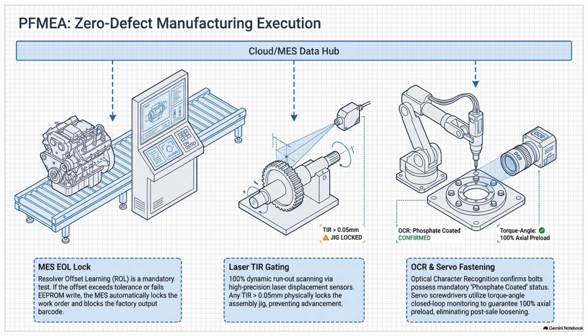The software then instantly mathematically corrects the nonlinear inductance. It counteracts the magnetic mirage in real time, ensuring the calculated angle used by the inverter is always perfectly orthogonal to the true rotor magnetic axis. It uses math to cancel out the physics. That is incredibly elegant. But the source document has one more design prevention, and this one really caught my eye because it involves adding completely new hardware.